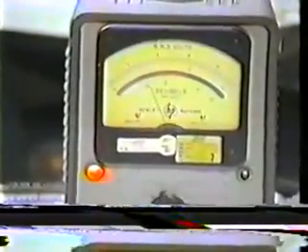Now, as you can see on the voltmeter here, we have a definite peak. So I'm sweeping the oscillator. If we go to roughly our half voltage points, we find we have a bandwidth of about a few hundred kilocycles roughly. And it peaks out at a frequency of almost precisely 2220 kilocycles. So what we'll do next is plug this into our equations and determine the speed at which our impulses propagate on the coaxial cable.